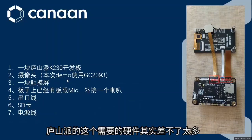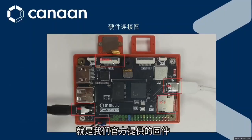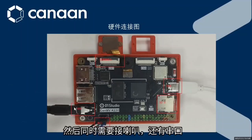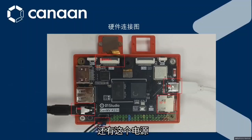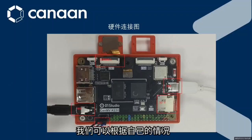For hardware connection, there is one key point to note. In the official firmware, the camera is connected to CSI1, so we must connect the camera to CSI1. At the same time, connect the speaker and the serial port, as well as the power supply and SD card. We also need network connectivity. Depending on your situation, you can use USB to Ethernet wired networking or use the onboard Wi-Fi.